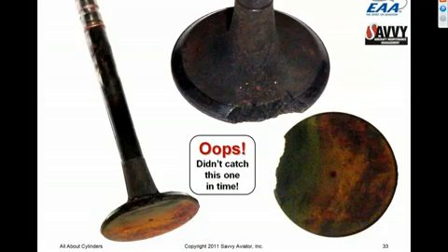Back then, this was a fairly common occurrence. Today, with borescope inspections and digital engine monitors, which I'll show you in a minute, there's no excuse for ever having a failure like this, because we have the tools to catch this stuff long before it goes to failure. But that's what it looks like when it goes to failure.